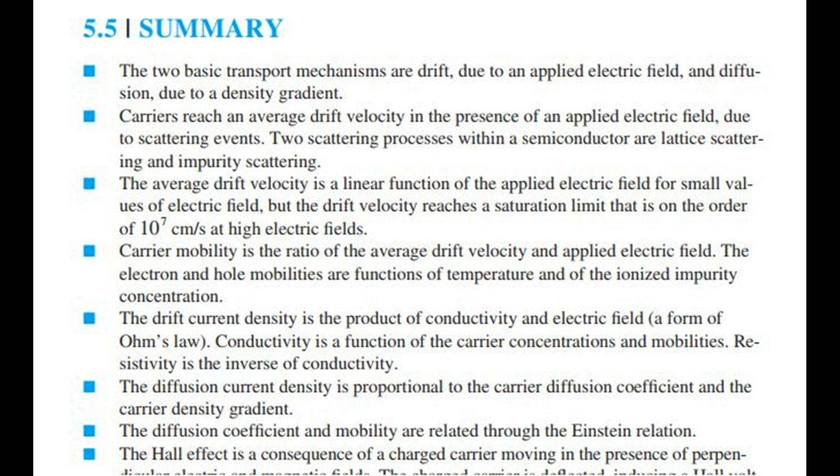The two basic transport mechanisms are drift, due to an applied electric field, and diffusion, due to a density gradient. Carriers reach an average drift velocity in the presence of an applied electric field, due to scattering events. Two scattering processes within a semiconductor are lattice scattering and impurity scattering. The average drift velocity is a linear function of the applied electric field for small values of electric field, but the drift velocity reaches a saturation limit that is on the order of 10 million centimeters per second at high electric fields. Carrier mobility is the ratio of the average drift velocity and applied electric field.